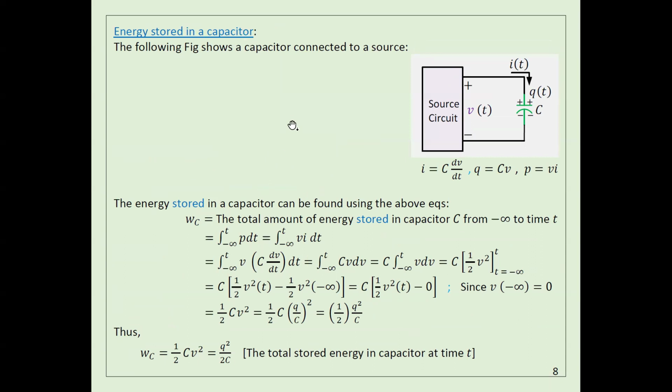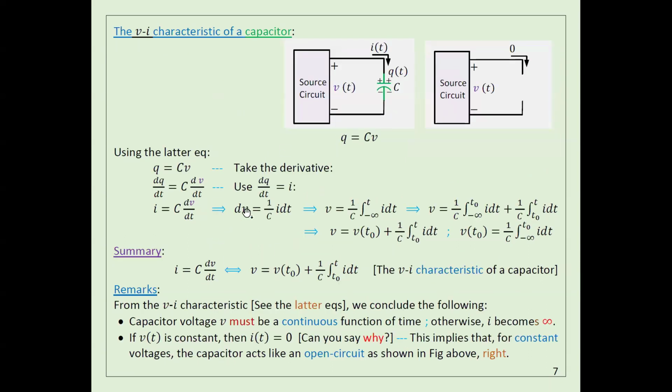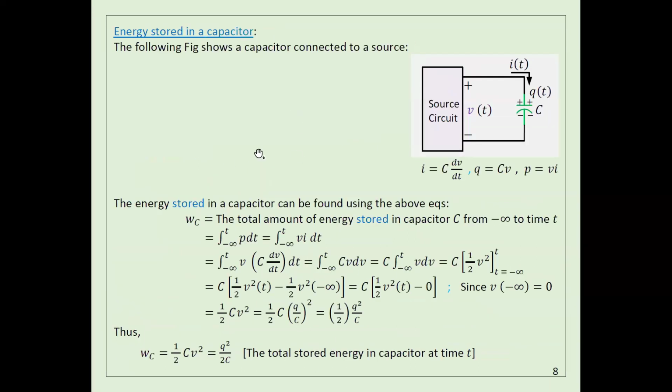The next thing, maybe I'm going to explain next time. So now I explained two main formulas. Q, the amount of charge on the plates, equals C times V. Also I equals C, the capacitance, times dV by dt, and this is the formula for I given V. What I'm going to explain next time is how we can calculate the energy stored by the capacitor.